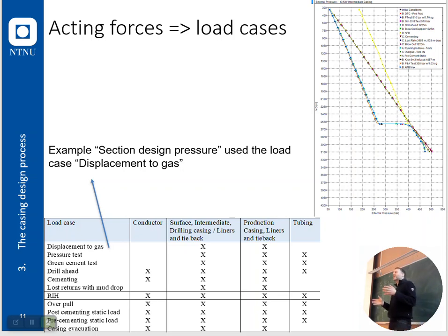And sometimes with drilling mud, it's very heavy, so you'll end up doing some strange stuff to know that the shallow parts of the well, because a gas filled casing has a very high pressure here. How are you going to test that with mud? It's going to look really ugly, right? You have to go to 154 bar here, and the density of the gas is like this, whereas with mud, it will go something like this. So you have extreme pressures in the bottom, pressure testing for this.